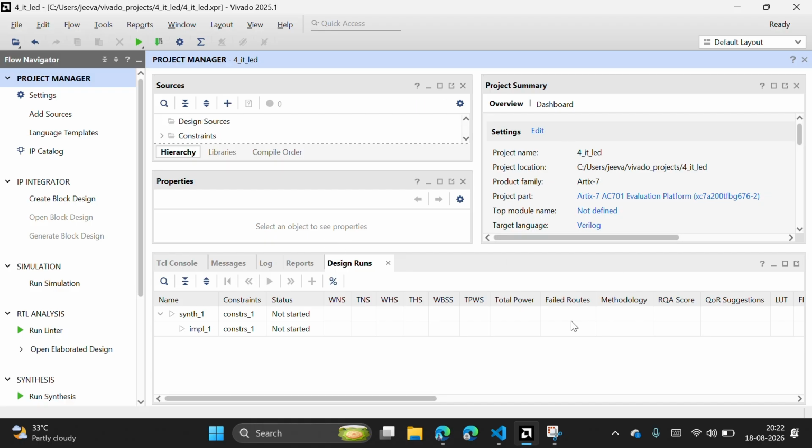And this is our view on the Vivado page. Let me give a small glance at what this view is, and then I'll go through the design next, so you can get an idea of what Vivado can do and the basic things we have to know in Vivado to generate a bitstream for an FPGA. Right here on the left of the page, we have the flow navigator, which has all the flow of the project.